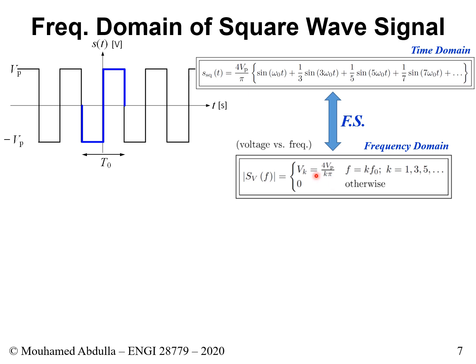Okay, and these spikes, if you will, appear at discrete points: at f0, not 2f0, then at 3f0, at 5f0, and so on and so forth. Only at odd multiples of the fundamental frequency. Anywhere else, at 2f0, at 4f0, or 6f0, 8f0, it's 0, right? So everywhere else, it's 0. Not only at these discrete points, but throughout the axis, beyond these integer values of k, it's also 0.